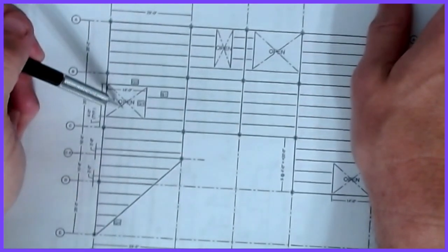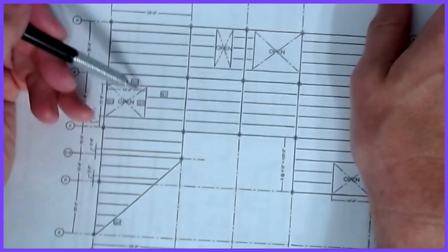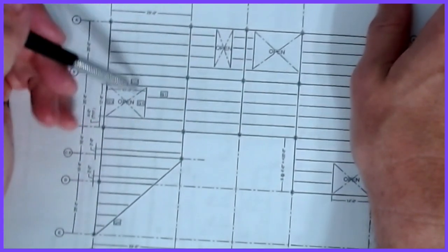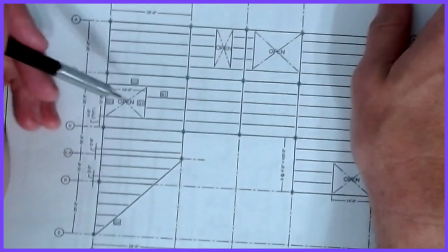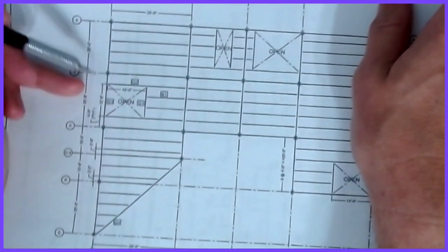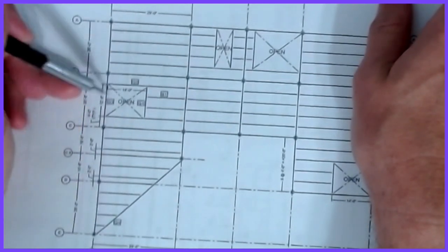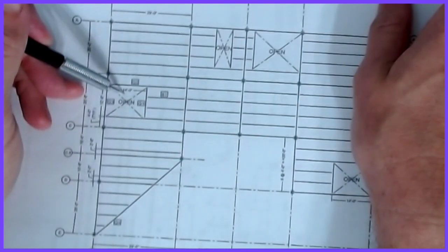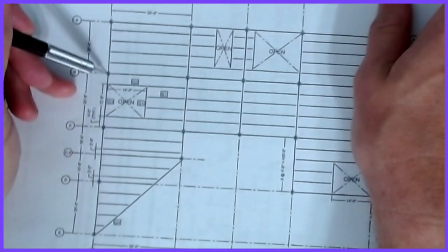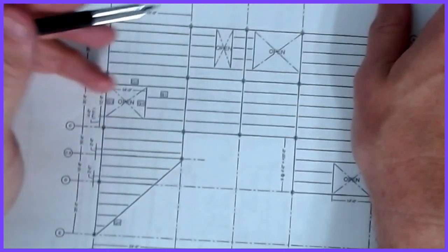Maybe there's a stairwell, or maybe it's an elevator shaft, that there is framing that can redirect loads around. And this is why you have to be a bit more precise when openings are involved. I can't do that average value very well, because this column, if you thought about doing the half, would take half, comes down to here and over, and most of that area is open, doesn't have any load anyway. So we would be overestimating this load and stealing it from some of the other columns in the same bay. So we've got to be mindful.